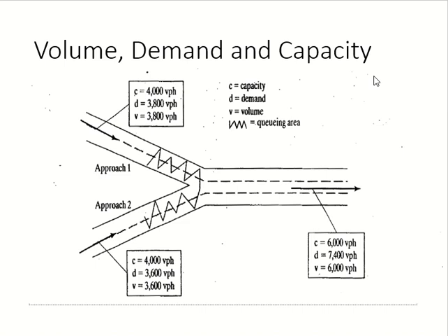Okay, we have seen some equations which can give you the trend or relationship between speed, flow and density. And yesterday we said that these equations are not applicable to interrupted flow conditions, because then we have stoppages, and these equations cannot give you zero because of a signal or because of a roundabout. But the actual flow will be zero, the equation will keep on giving you some numbers.